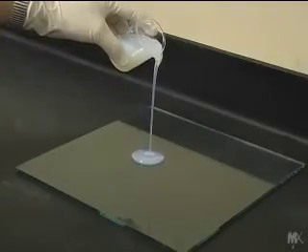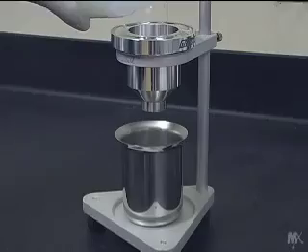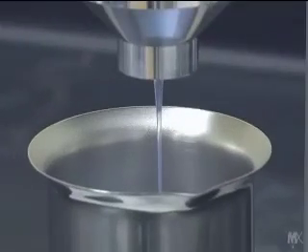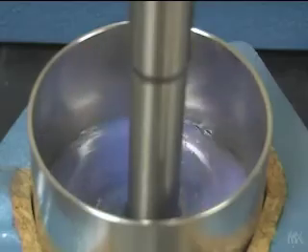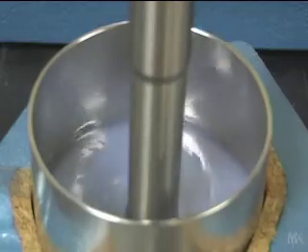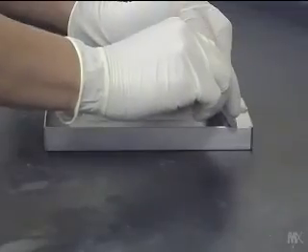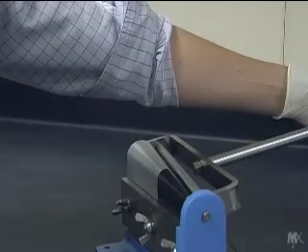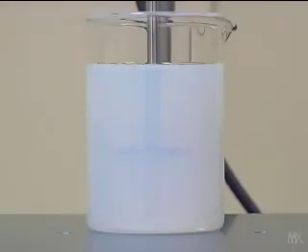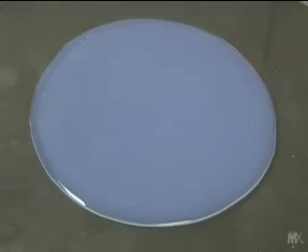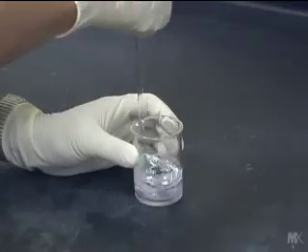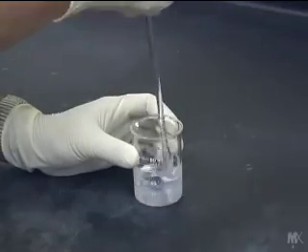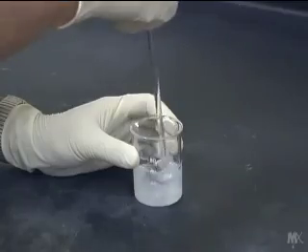Kaneka Texas Corporation has developed a process wherein the individual 0.1 micron CSR particles are dispersed and maintained in the matrix independently. The Kane Ace MX product line allows epoxy processors for the first time to easily and cleanly employ core shell rubber in a multitude of applications. Kane Ace MX products are extremely stable and can be stored for years without agglomeration. Formulating is easy. Kane Ace MX can be mixed into a system in just minutes with normal stirring.